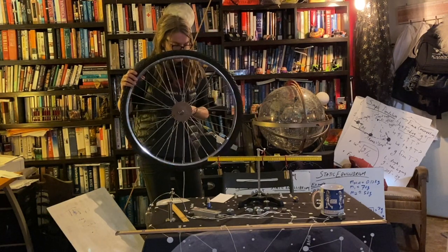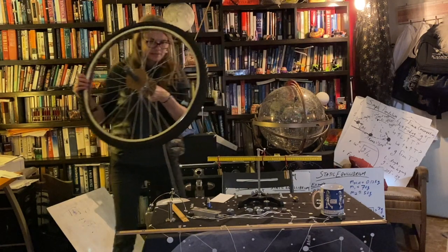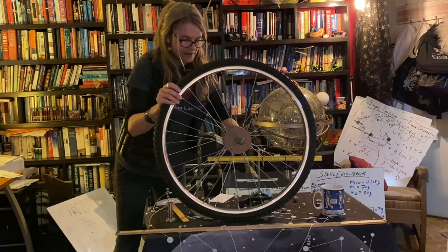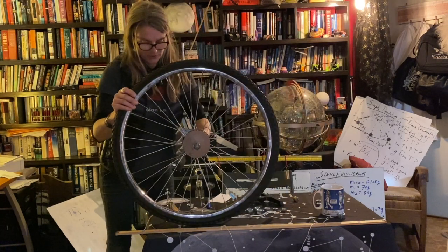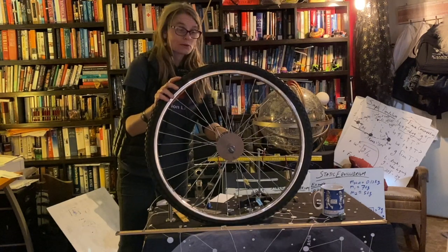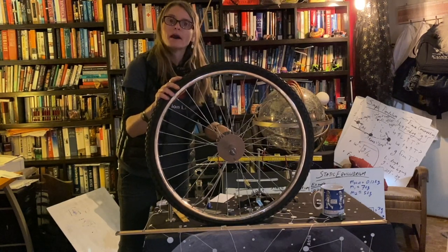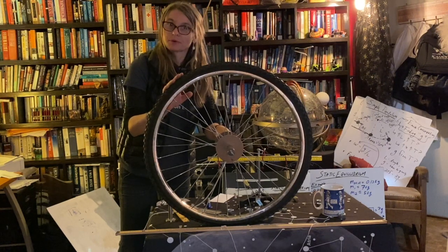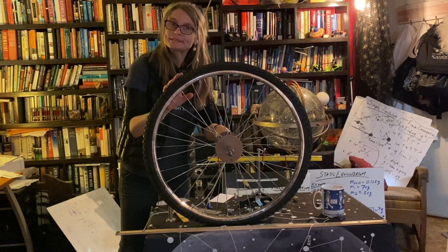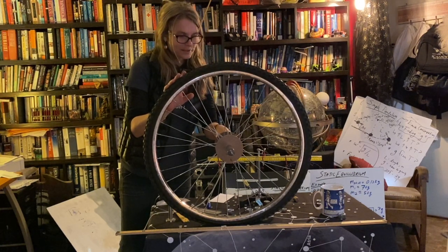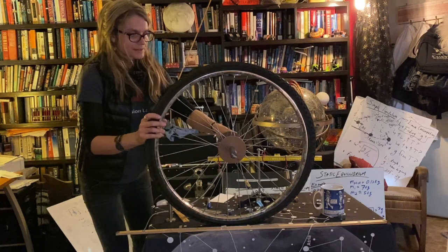So let's put a stop to it, slow it down. There again is an example where my torques don't sum to zero, but my forces do. Now what if I had a skidding wheel? So let's skid this wheel. In that case, if I can slow it down or speed it up, then my sum of forces is not equal to zero, but the sum of my torques is equal to zero. That's the case where I only have my translational forces not equal to zero, but my torques are. So that's a big difference.